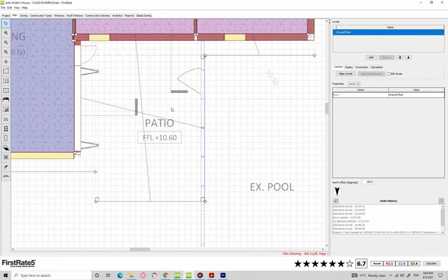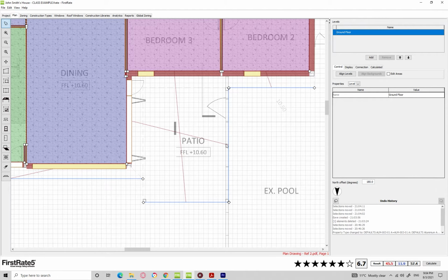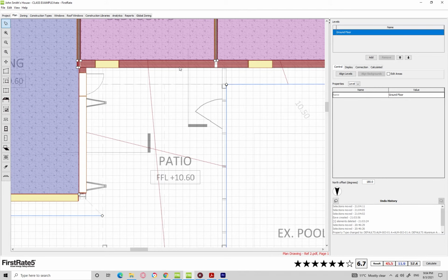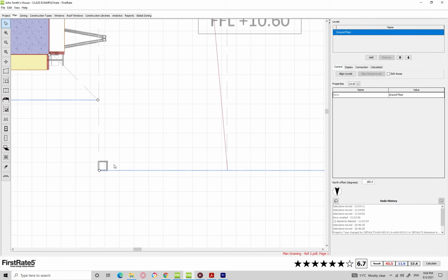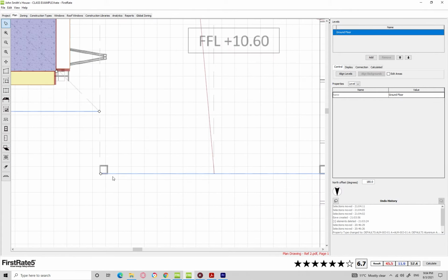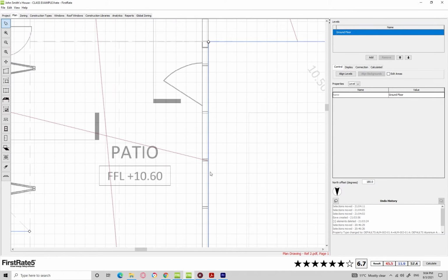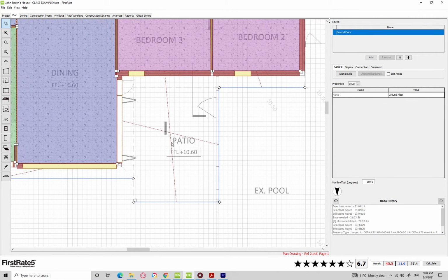You can use the same technique when you're drawing your patio structure. That was another question that came up in class. What if I have a patio or al fresco or any sort of open outdoor structure that could impact the amount of sunlight that my house, my enclosed building area, will be receiving? Well, you can also use the Eave tool to represent where that structure is. So here we can see some columns, these here, and these lines here represent the roof above the patio, and we are associating each one of these eaves back to a wall of the building.